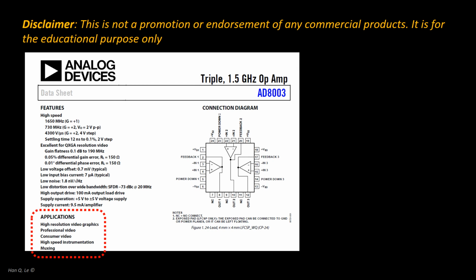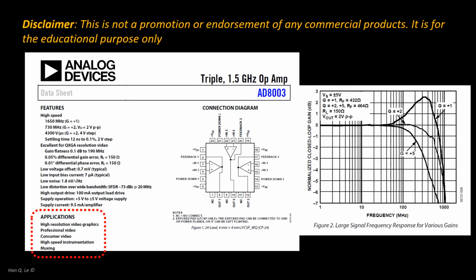The first thing one should look at is the spec sheets. Since frequency is important for this application, the one thing to check out is the frequency response chart. Each gain has a characteristic frequency response curve, including a 300 MHz resonance for gain of 1. We will learn the concept of resonance in Lab 6.